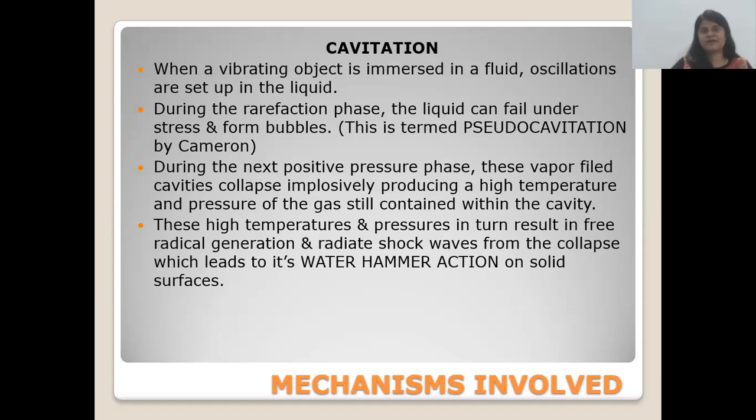Cavitation: when a vibrating object is immersed in the fluid, oscillations are set up in the liquid. During the rarefaction phase, the liquid can fail under stress and form bubbles, which is also known as pseudo cavitation. During the next positive pressure phase, these vapors fill the cavities and collapse implosively, producing a high temperature and pressure of gas still contained within the cavity. This high temperature and pressure in turn results in radical generation and radiate shock waves from the collapse, which leads to water hammer action on the solid surface.